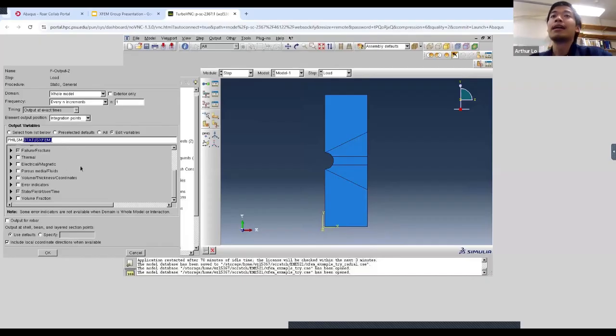But more importantly is STATUSXFEM, because we're dealing with the XFEM method. So evidently this is important. So STATUSXFEM essentially is a variable that gives the status of those enriched elements that are involved in the crack. So if the status is 0, the element is undamaged.